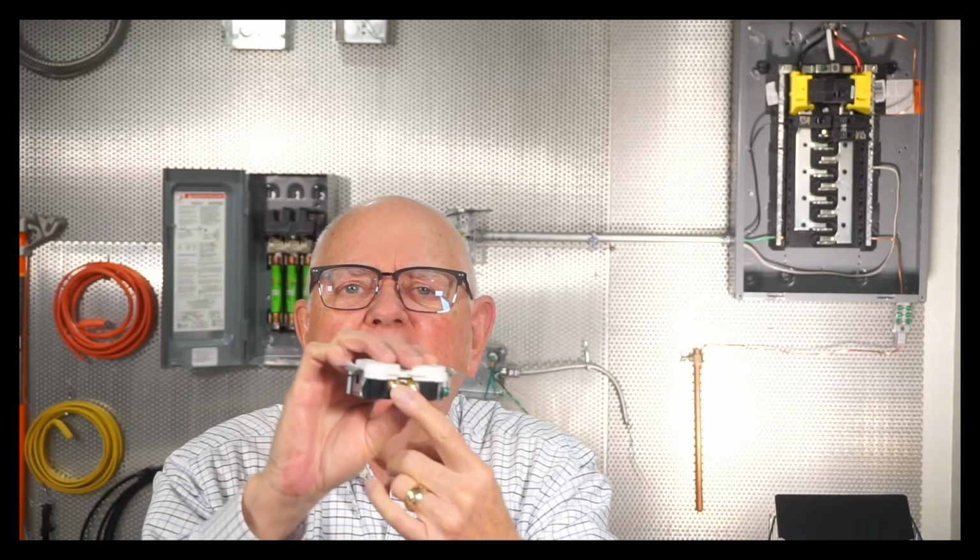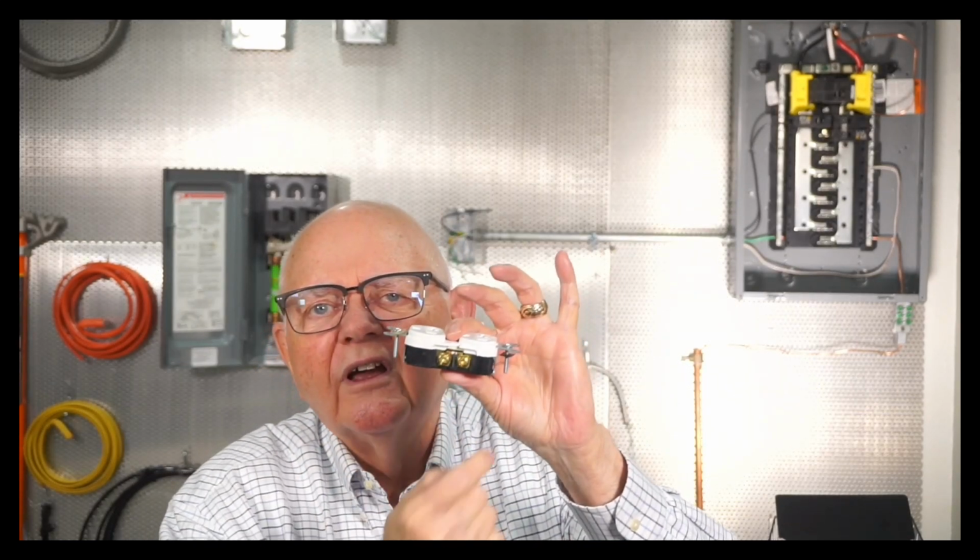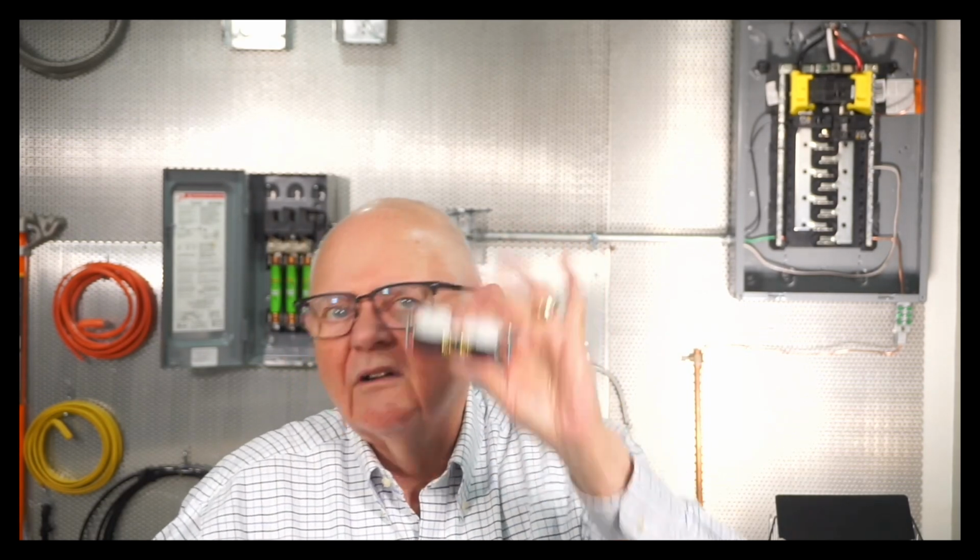And where I connect my neutral on the other side, if I read from any line to neutral, I get my 120 volts, or I have a difference in potential, don't I, from line to neutral. So by definition, that's the multiwire branch circuit. And we're going to see there are some specific requirements for multiwire branch circuits in Article 210 as well.